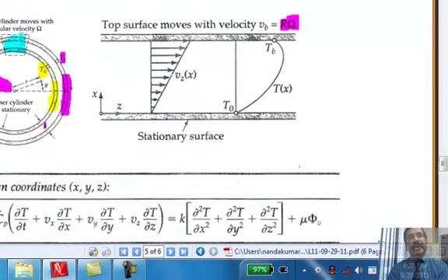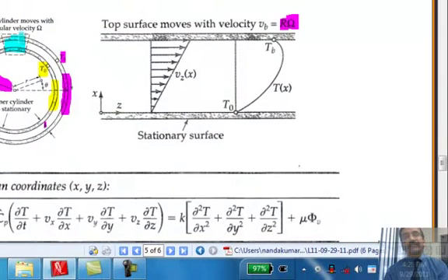So, physically, do you understand what is happening? What is the velocity profile for that problem? It's linear. We already know that. We have already solved that problem. This is the Couette flow: the bottom plate fixed, the top plate moving under steady condition. We have actually studied the transient one also. This is under steady condition.